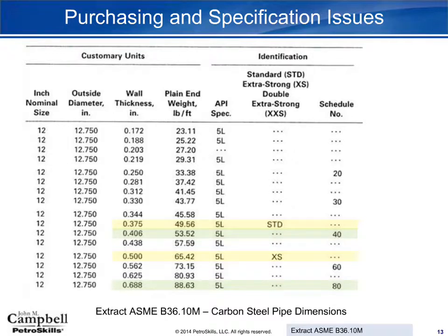So please make sure that when you're running through your specs, you call out exactly what you intend to. I have seen client specifications where the wall thickness itself, the 0.375, is called out on the piping spec to avoid any confusion. So make sure this follows through, not just your purchase orders. I also like to see that kind of information on isometrics going out to the field as well.